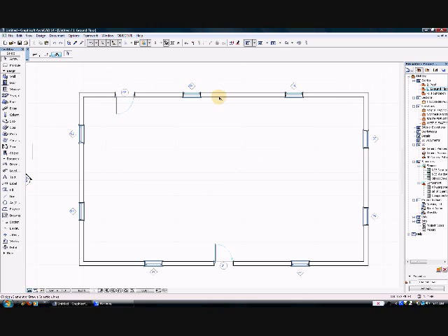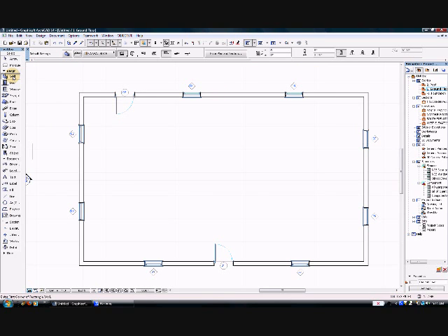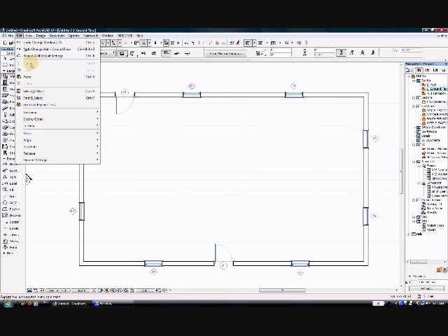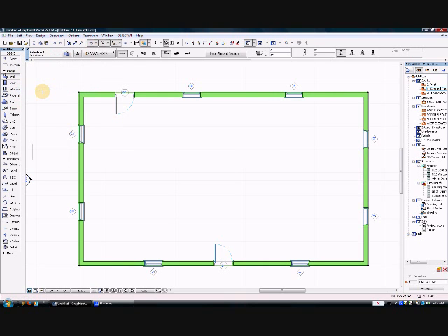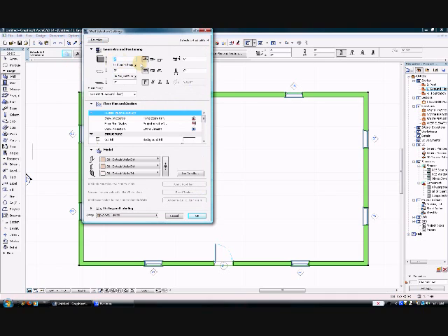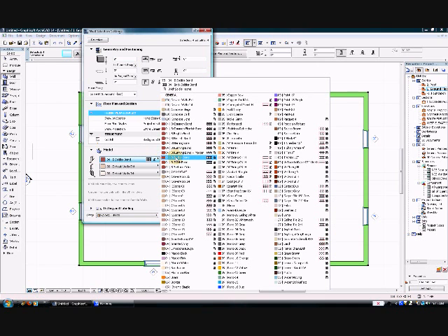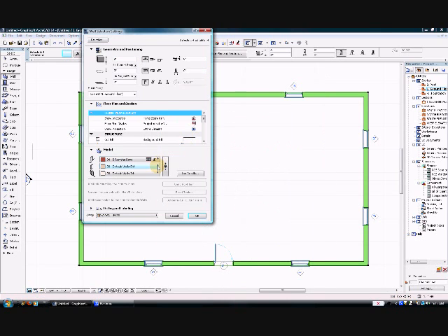So let's go to the floor plan, click on the wall tool, go to Edit, select all walls, and in the settings dialog we'll see that these are 8-foot walls, level set to 0. We'll change the thickness in a minute. The material we need to set to running bond on the exterior and edges.